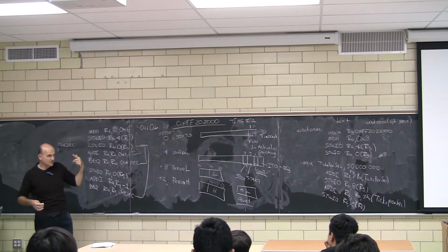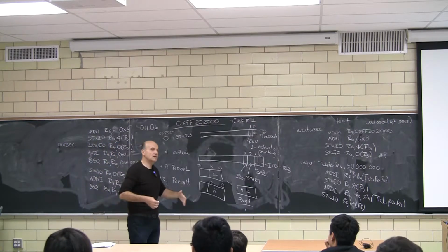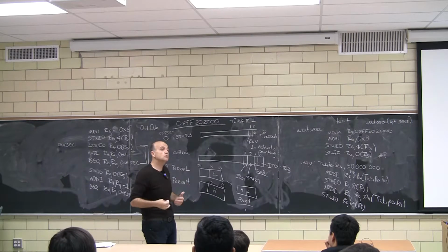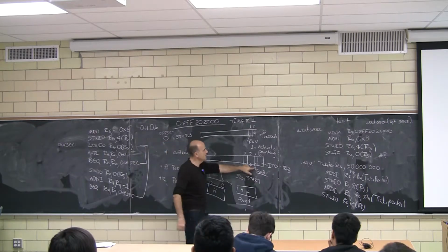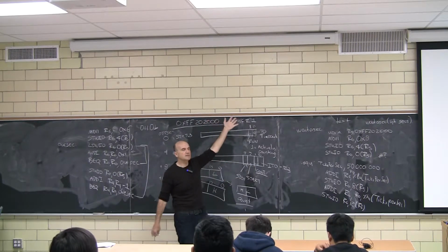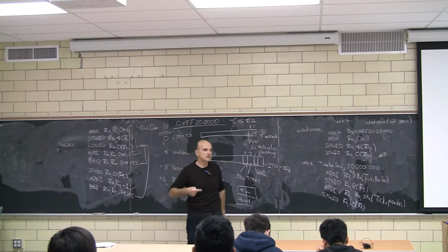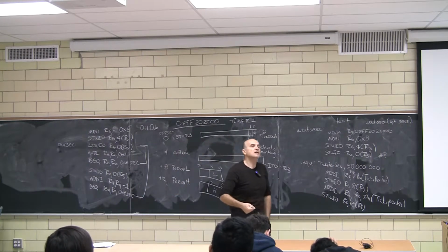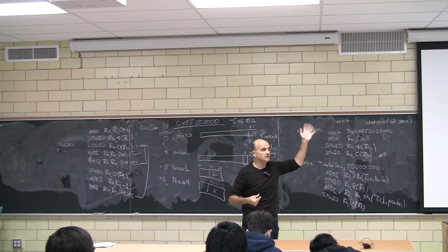This is exactly why we use the continuous mode on the timer, so that it resets itself and starts counting the next second without waiting for us to look at it. The continuous mode says, look, I'm going to raise my hand and say I timed out. Whether you look at me or not, I don't care, I will count the next second. So the timer does that in real time. The moment the first second elapses, it starts counting the next second without waiting for you to look at its raised hand.